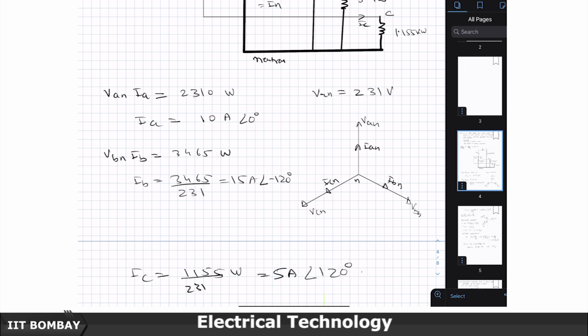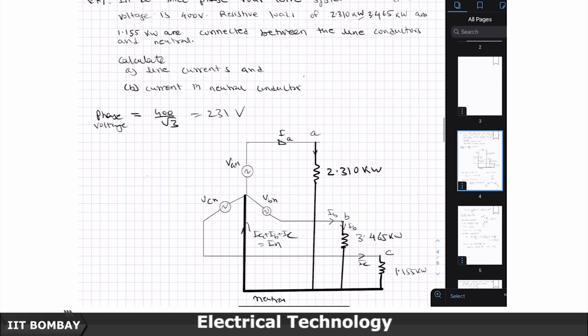So, you see that this causes the current unbalance, which causes current to flow in the neutral conductor, again makes your distribution system unnecessarily lossy, and that is a societal loss. We have talked about this earlier. So, balance is always useful, balanced system operation is always useful in giving an efficient system operation.